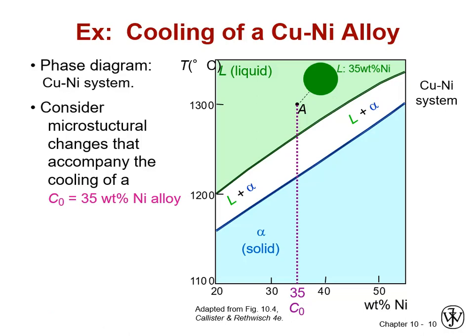So we're going to use little circles as sort of schematics of what's going on in the microstructure, and these evolved over the years of optical microscopy, where we could actually image what was going on in the microstructure after the fact by rapidly quenching samples and then doing optical microscopy and taking pictures. So we're going to show a series of circles that would be basically representational microstructures as if you had done optical microscopy on the microstructure.